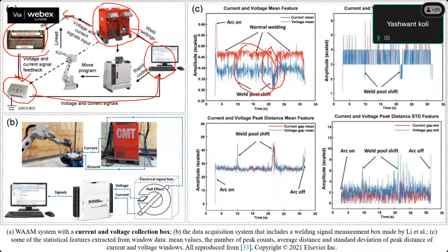Another defect we can categorize is incomplete penetration and humping, which is very common. It's like a camel hump. If we set a high heat input parameter, humps are created during the layer deposition. If these humps are seen, they are also a defect, an aesthetic defect during WAAM fabrication, which is not wanted.